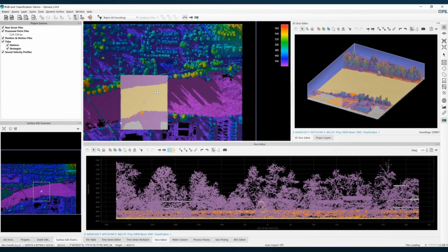And then the interesting thing about this is if I have those LAS files, I can unload my edits and also reclassifications back to the LAS file so that I walk away with the same file. It's just a little bit better than it was when it first showed up to Qimera. You can also re-export them as a brand new LAS file. That'll have your cleaning edits and the classification changes done as well. So you could use this to start doing classification work of your bathymetric LiDAR data and even terrestrial LiDAR data. There's quite a rich tool set in the community for terrestrial work. We tend to play the sweet spot and be in the water and on land a little bit, and that's where we tend to focus our work with LiDAR.